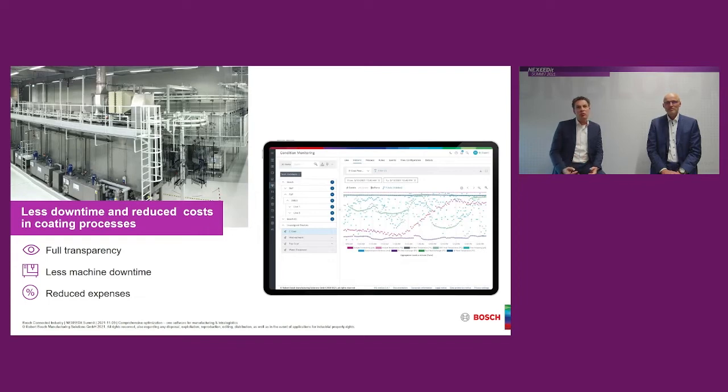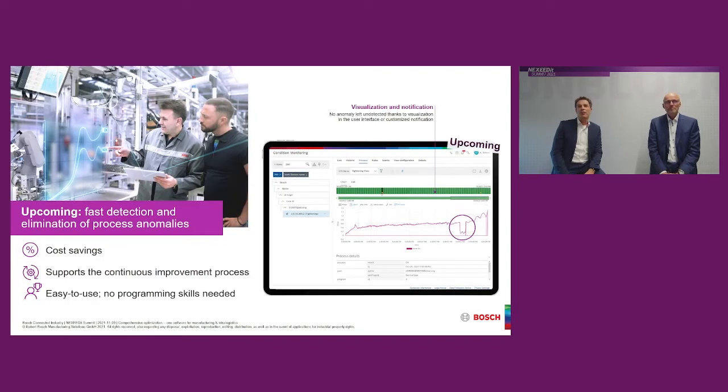And with condition monitoring from the Nexeed IAS, important parameters such as the temperature or pressure can be monitored centrally in real time. And thanks to the warning messages, maintenance staff now know at an early stage when a filter is beginning to clog, yeah, and they can react before it's too late. Just one example outside of Bosch.